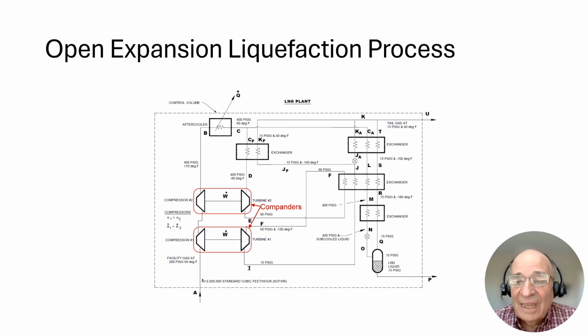distribution system. And your distribution system has to be capable of taking this large amount of gas pretty much 365 days a year. Because if you want to run this refrigeration process during, let's say, July 4th, when no one is using gas, everyone is out watching the fireworks, well, you've got to take all of this gas, and in this particular case, I'm looking at 2 million standard cubic foot of gas per hour.